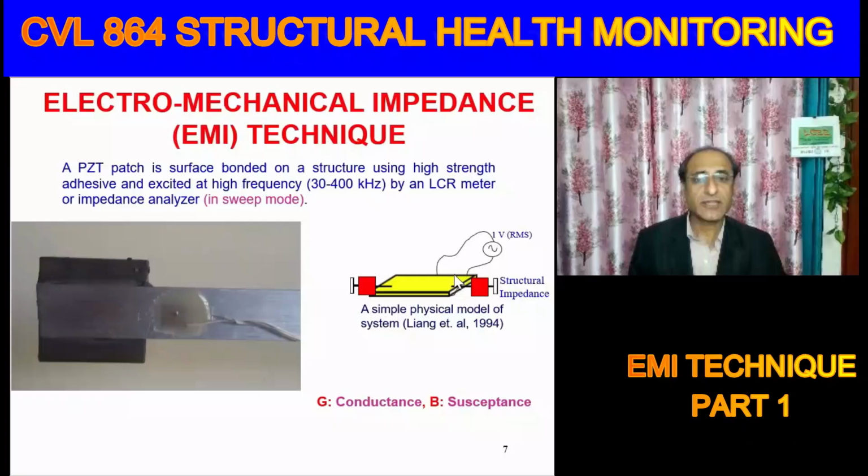So what we do is, as the patch starts vibrating, it also interacts with the structure. So first of all, we are making the patch excited, so that means we are using the converse effect. So converse effect means that the structure is now set into vibrations. But then because the patch is connected to the structure, the structure also influences the patch. And as a result, because this is not a free piezo, as a result of the interaction between the structure and the piezo patch,